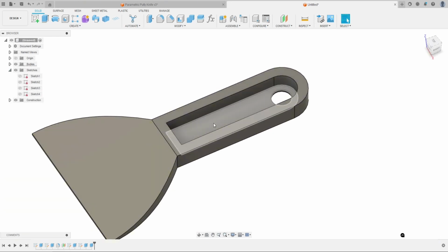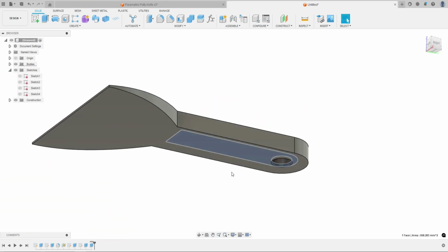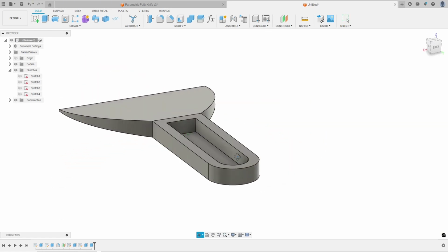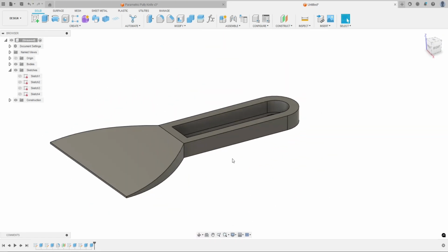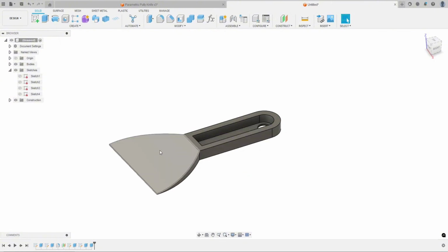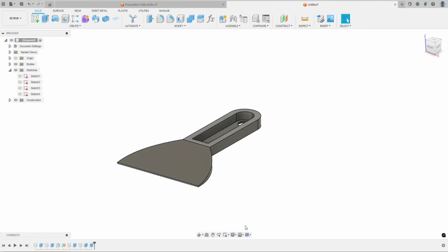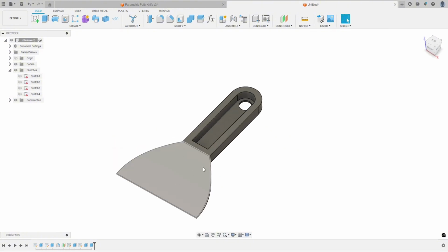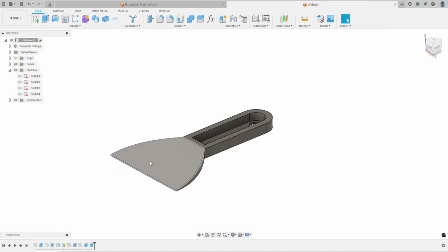And if we just click on this face, hold shift, click on the bottom face. If we come down to this right, we're at 1 millimeter. So no matter how thick we make this handle, this will always be 1 millimeter. And like I said, that just saves a little filament. You could probably do the same thing for the blade. You could have two big rails coming down here to give you the strength, and you could hollow out maybe some of the center of this blade as well, and that would save some more filament.